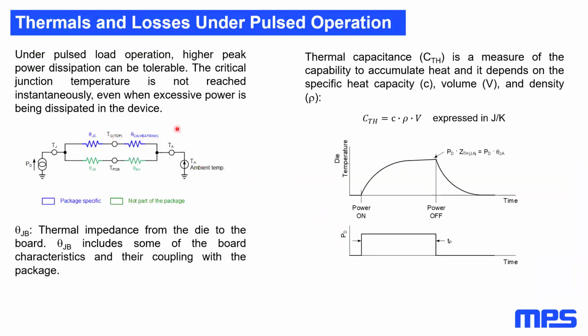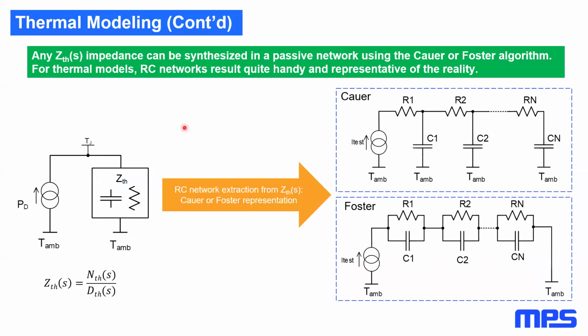So let's say if one has done an experiment on an existing package, on an existing device, one can really understand how much each part of the device under test contributes to the thermal impedance, and could also identify how much the PCB, which eventually is what is in the power of the electrical designer, influences the total thermal impedance and thermal resistance. I hope that answers the question.